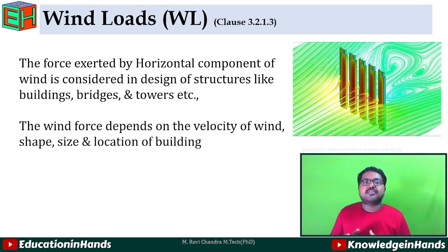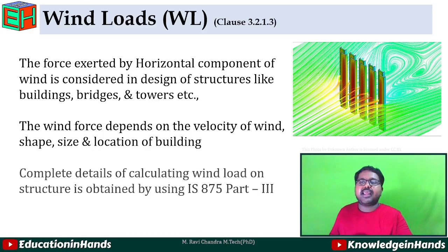The wind force or wind load mainly depends on the velocity of wind, and the shape, size and location of the building. If we consider two buildings, one on a hilltop and one in plain terrain, those two have different wind action. The building on the hilltop will experience more wind load than the one in plain terrain. So it is an important consideration in wind loading. The complete details of calculating wind load on structures are obtained from IS 875 part 3.